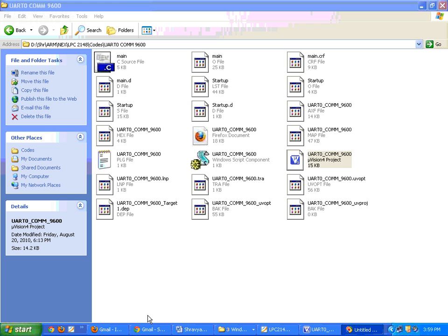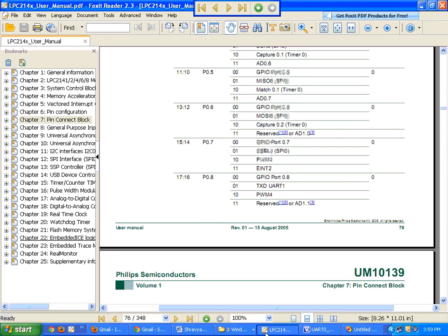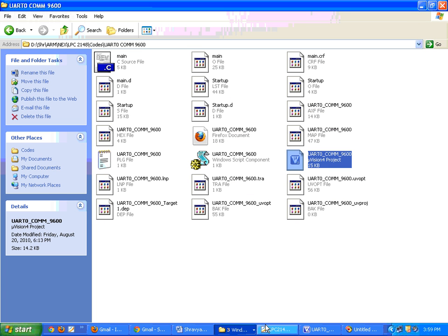So UART is one of the peripherals of our ARM7. Because it is one of the peripherals, to write programs you need to configure a set of registers in UART. So what registers you have to configure, you have to go through the data sheet. So the first step will be to see what all your pins are by default: input or output pins.